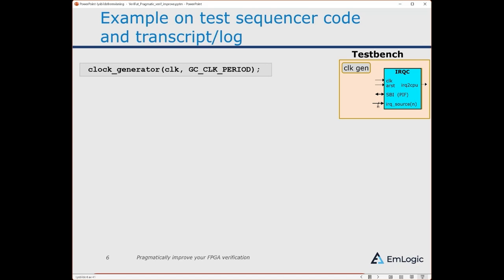When you call that procedure in the architecture, it doesn't work as a sequential procedure as you normally do in a process, but it works as a real separate standalone process. So this procedure inside the architecture is a so-called concurrent procedure and allows you to do a very, very efficient reuse of processes. So now you have a clock generator, and of course you need your test sequencer that is going to handle your test sequence from start to finish.